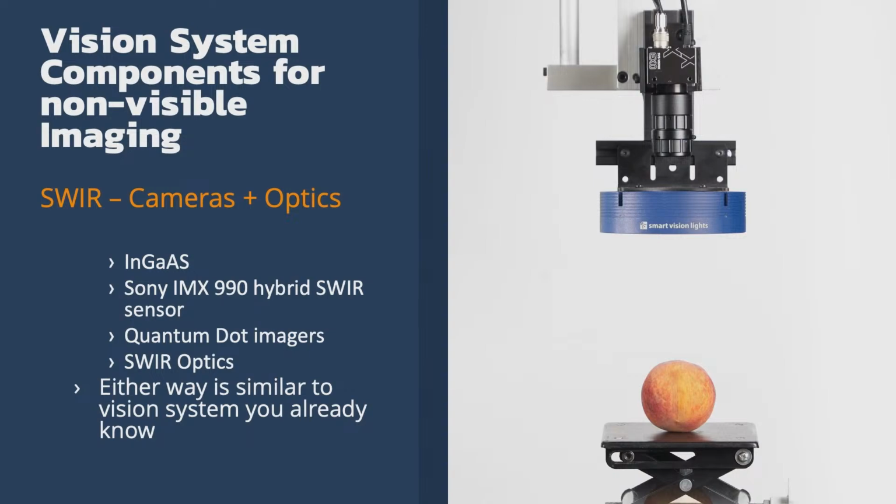Similarly, we see a SWIR imaging system on your screen now, and you'll notice it doesn't look that different. In this case, we do have to use a SWIR specific camera, and this is a Teledyne DALSA with a Sony IMX 990 hybrid SWIR sensor in it. And this is because the shortwave infrared does not register on silicon. The near infrared at 850 or 950 nanometers will register on some visible sensors, but largely it takes a specialized sensor to capture the shortwave infrared spectrum.